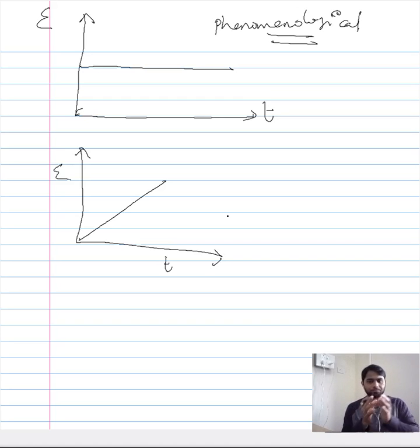And we saw that the slope characteristically varies for each of these regions. In order to study the whole creep curve, we section it into different stages, and we focus on each stage and talk about the theoretical reason for the behavior of the material at that stage. For each stage we do the same, and then we combine them to understand the overall creep curve. This is the approach we take to study the creep behavior of the material, and it is referred to as the phenomenological approach.